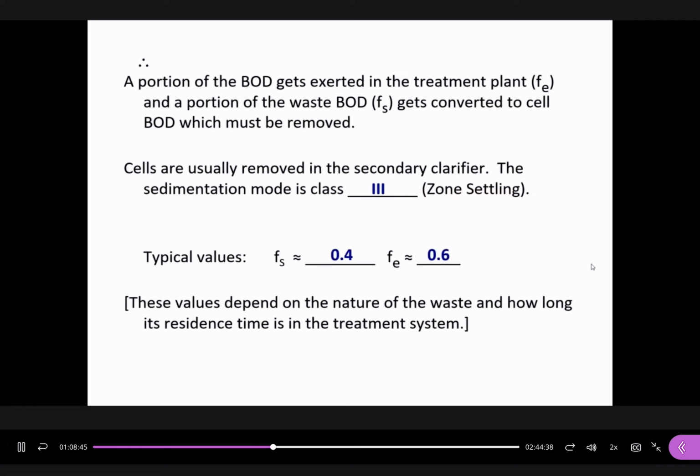Right. So the philosophy here is we have wastewater organics, right? They are contaminants. They are not desirable. We utilize microorganisms to degrade them. One portion is degraded into CO2 and water that produces energy, and one portion is converted into cells, new cells, right? Does that make sense? And the cells are COD. Cells are COD, right? Therefore, we cannot directly discharge the cells into our environment, right? So we need to remove the cells before they are discharged into our environment.